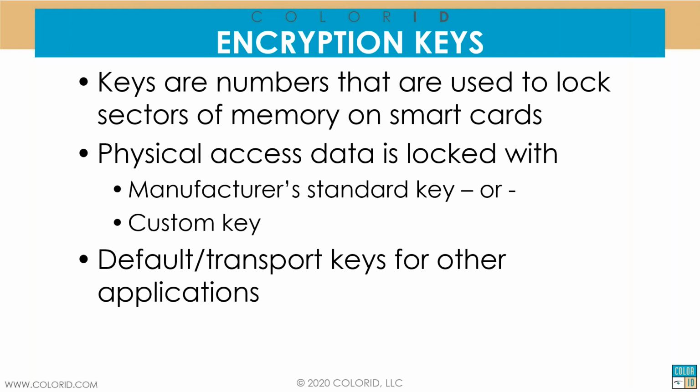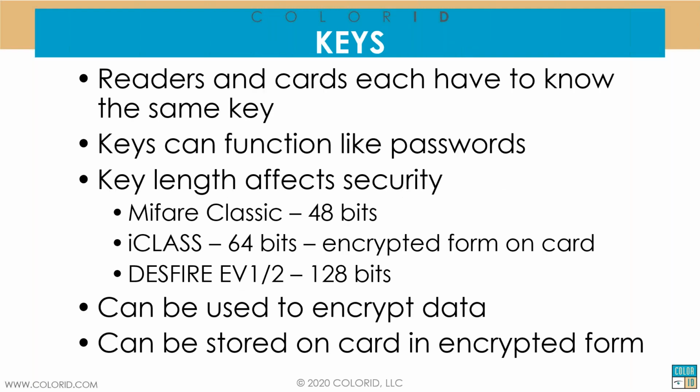If you don't have areas of your card encrypted, then they're usually just locked with what's called a default or transport key. And then often it's just ones. And so if you have a MIFARE card and you want to program some unprogrammed areas, you need to unlock those areas for programming. What's the password? All ones, type it in, boom, you're in there. You can replace that with your own password or with your own key.